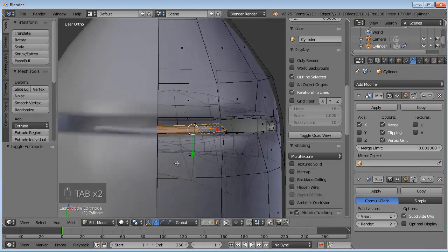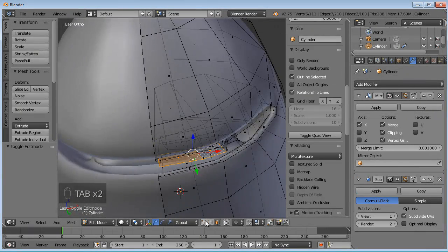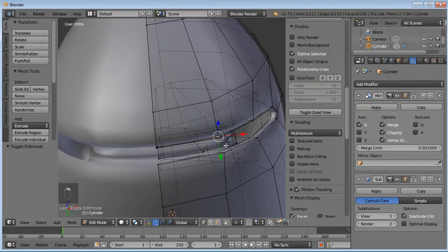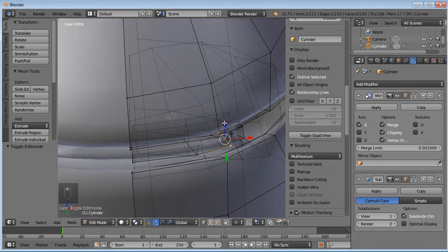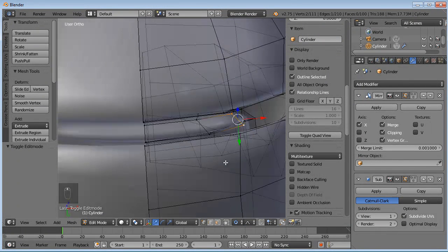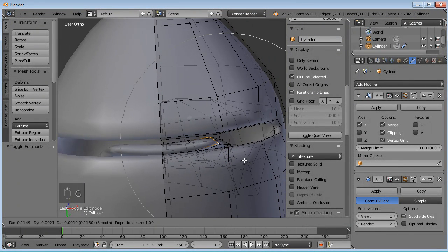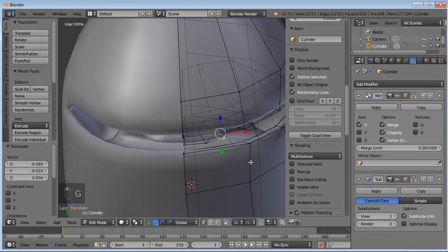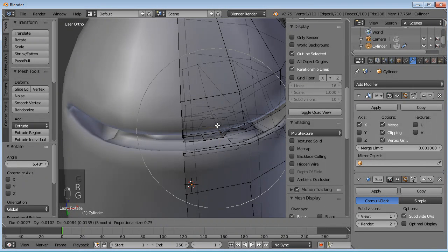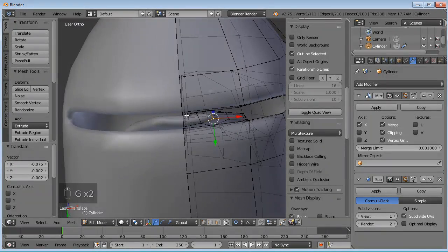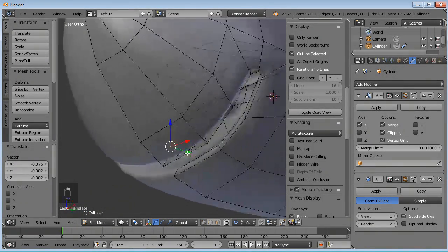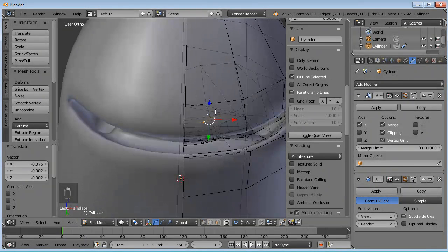Well, it's kind of squared off. Let's round that if we can. Go ahead and grab the corners of it. There we go. And if we hit Alt-O on our keyboard, Alt and then the O button right next to the P, not the 0, that'll add what's called proportional editing. And that's kind of just a gradual falloff where you can move vertices, and it moves the ones that are nearby as well in a gradual falloff type of thing, so you get a nice smooth movement